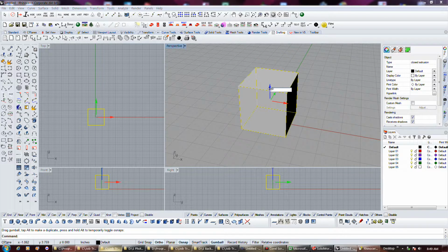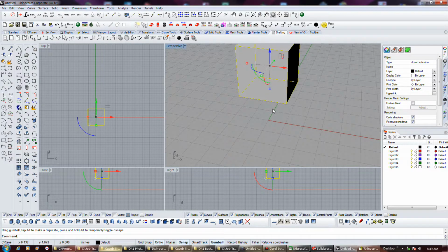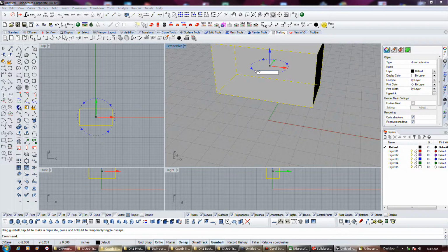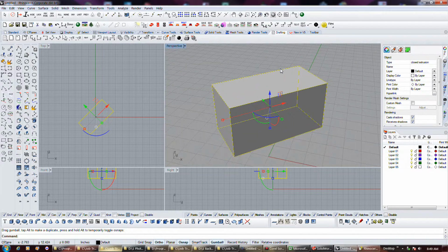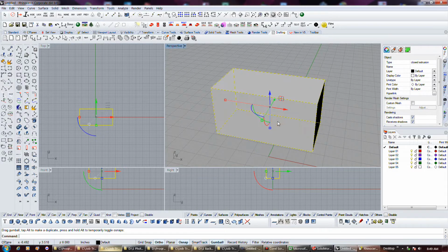If you click on it, I can move it up by 2 units. And if you click on a scale handle, I can make it wide by 2 units. Click on a rotation handle, I can rotate by 45, and you just right-click your mouse button outside of that box, and that's the same as pressing Enter, if for some reason you don't want to press Enter.